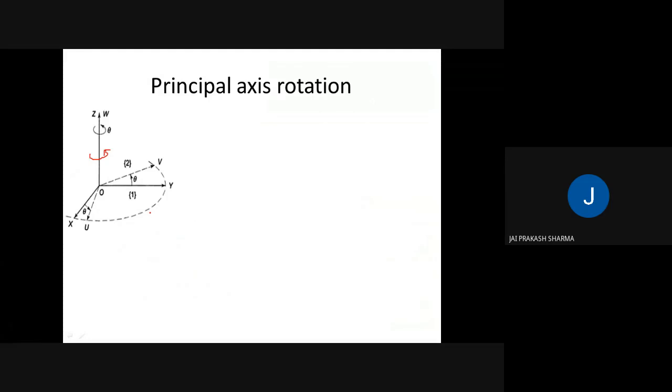For evaluating the final position of the tool, we consider these different frames. With respect to a body arm, we use the principal axis rotation or principal axis frame. With respect to an end effector, we have a Euler angle representation, which may be a movable axis frame. If we want to calculate or perform a rotation, we have to perform such operations with the help of matrices, which can ease our analytical part.